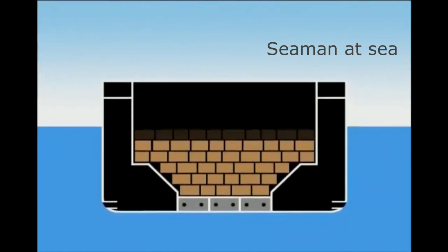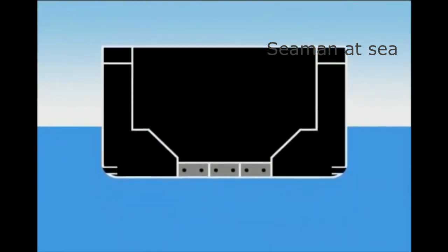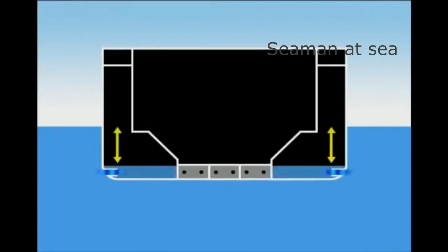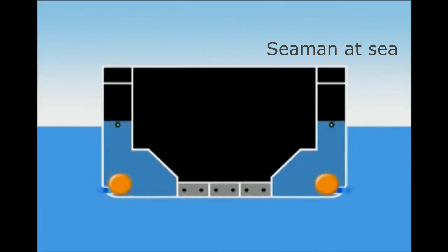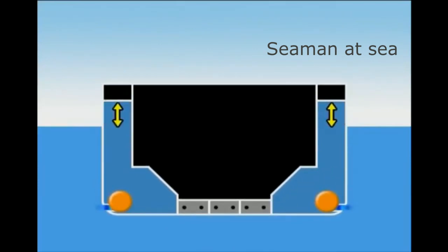As cargo is unloaded, and the water level inside the ballast tank becomes lower than the sea surface, ballast water is gravity filled into the tank thanks to water pressure head of the seawater. Ballast filling stops when the water pressure head becomes zero, as the ballast water level rises to become equal to that of the sea surface. To continue to fill ballast water further from this state of balance, it's necessary to pump water in with a water pressure head higher than that inside the tank.